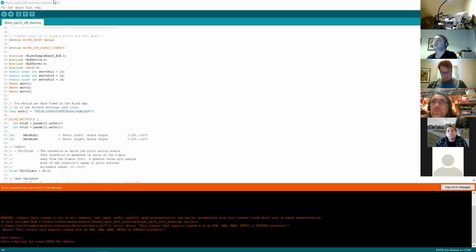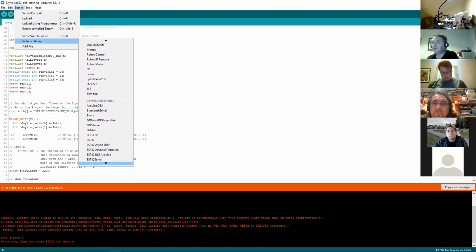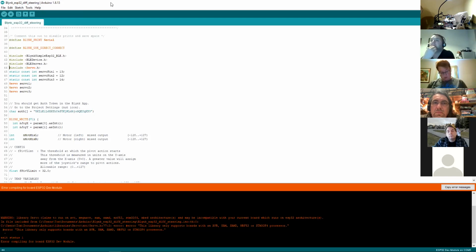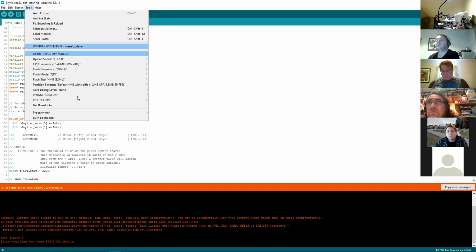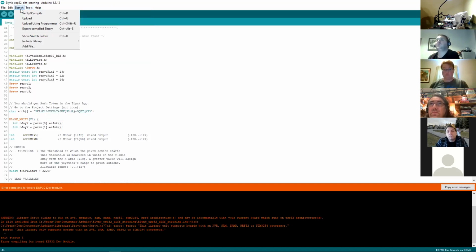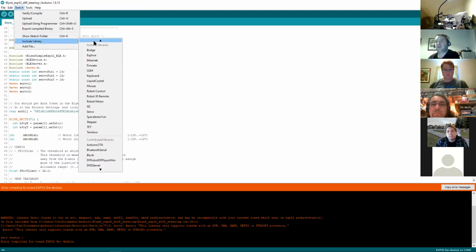Right, yeah, because I see that in your code you've got it labeled as servo.h. I think I've got the ESP32 servo one. It's called Servo ESP32, the one that I've used. Right, okie dokie, I will have a look for that in a moment. In my rush to play around with it, I just downloaded the first one that I found, and it's called Servo ESP32. There are 3 examples that come with it. There's not a lot of documentation on those, but if you just Google ESP32 servo, you'll find it. And would it just be a case of changing servo.h here to that particular library?